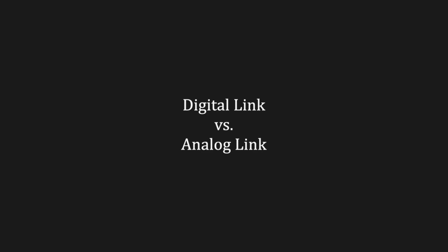In a studio, one of the most important connections is linking hardware devices so digital audio can pass between them in real time. A digital link is always better than an analog one because it keeps the signal pure, while analog adds quality loss from digital to analog and analog to digital conversions. To send digital data, you need both a data channel and a shared clock for synchronization. One cable can handle both, but when several devices are used, it's better to have a separate master clock. The connection also needs an audio format that both devices understand.